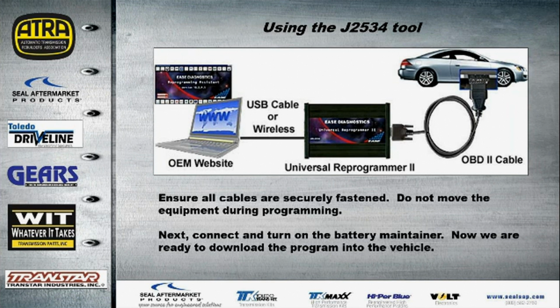We want to make sure all of our cables are securely fastened, all the lock tabs are locked. Do not move the equipment during programming. Anytime you move a wire, you create a magnetic field. If you're passing two wires, that can actually interrupt your programming, and you'd never know it. You say, all I did was move it. Yeah, buddy. So just keep that part in mind.